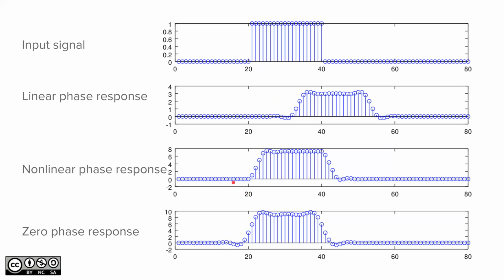If you have a nonlinear phase response, this resembles a bit the analog systems, since in analog systems you don't usually have this preamble, the undershoot before the signal starts rising. Here the signal starts rising, and then it overshoots and then settles here. And when it goes down, it undershoots and oscillates a little bit and decays out.